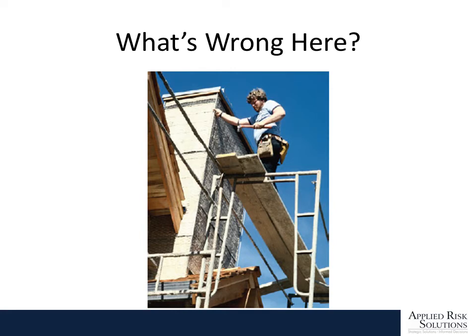What's wrong here? Well, obviously, he's got no personal fall arrest system. He's got no guardrails, no toe plates. This is pretty much a very, very serious OSHA violation. And the individual has put himself at great risk of a fatality.